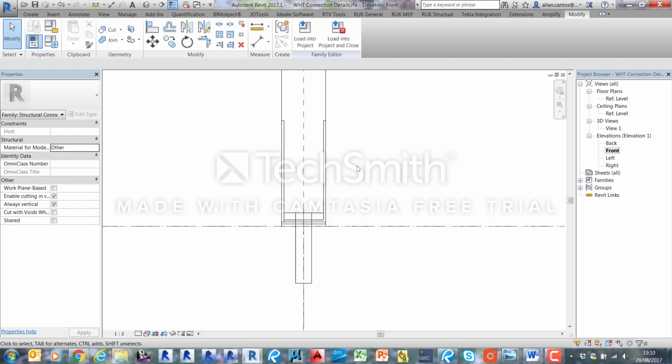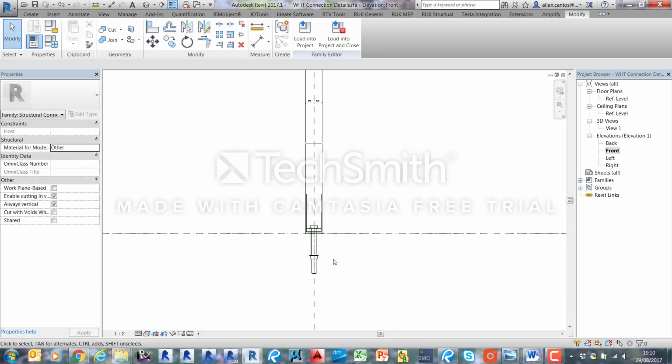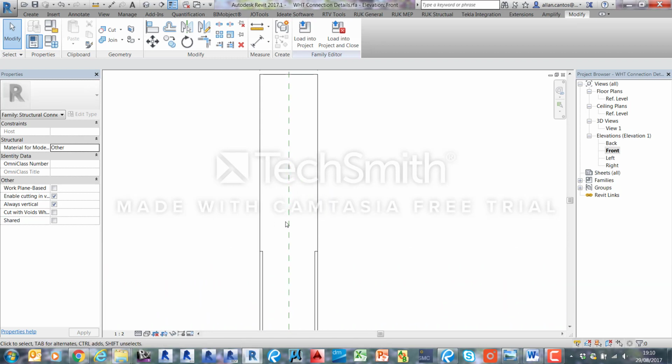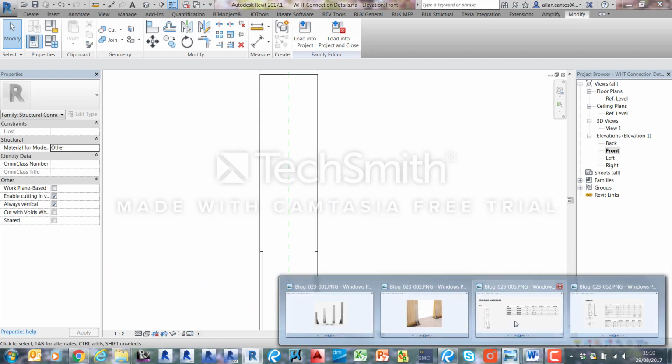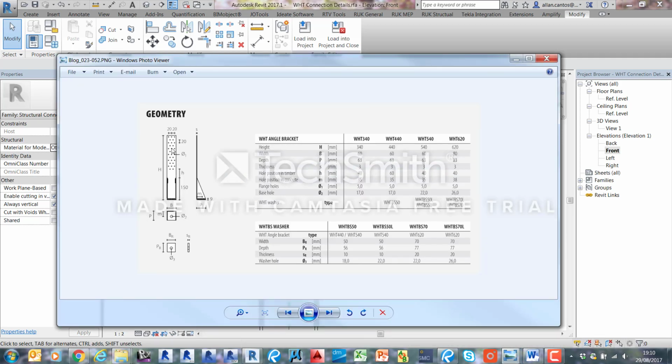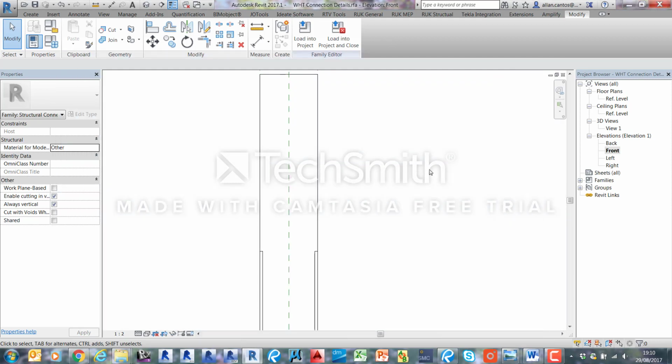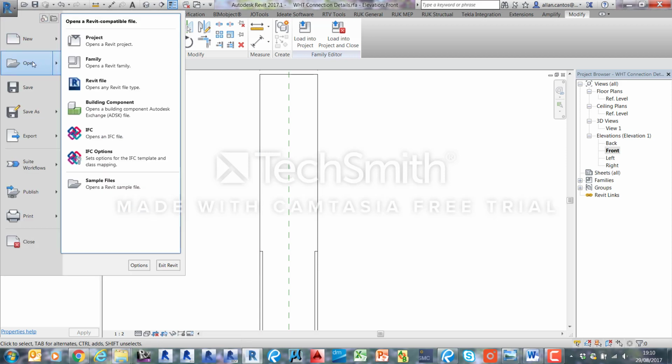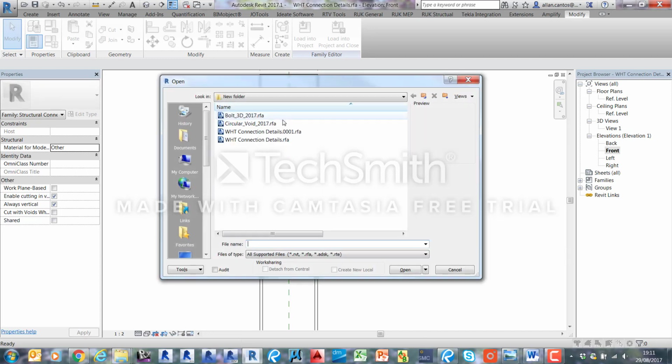Next, go to front view and we will start creating the holes, which are these small holes here, flange holes diameter 1, which is 5 mm diameter. I will be also sending you a link of this hole family that I will be using in this exercise. So I will be sending you the link for these two families that I use in this exercise for you to download.